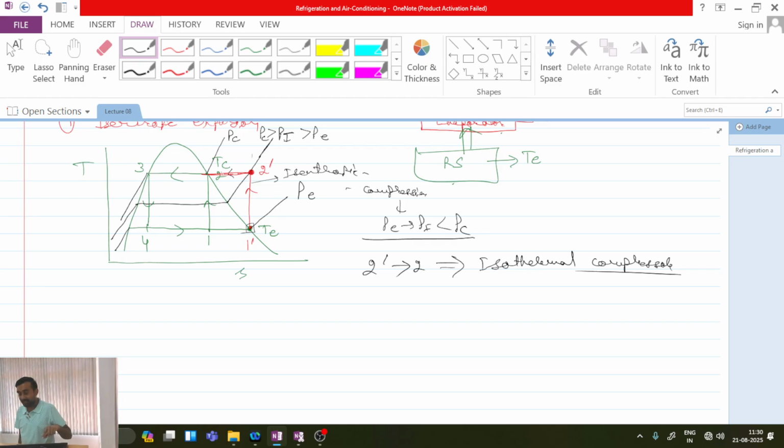So here the isothermal compressor should operate at very low speed. In a complete closed loop cycle, one device wants the working fluid to move fast, the other device wants the working fluid to move slow. Can there be continuity of flow? No, not possible. And of course, the other two limitations you have clearly indicated.